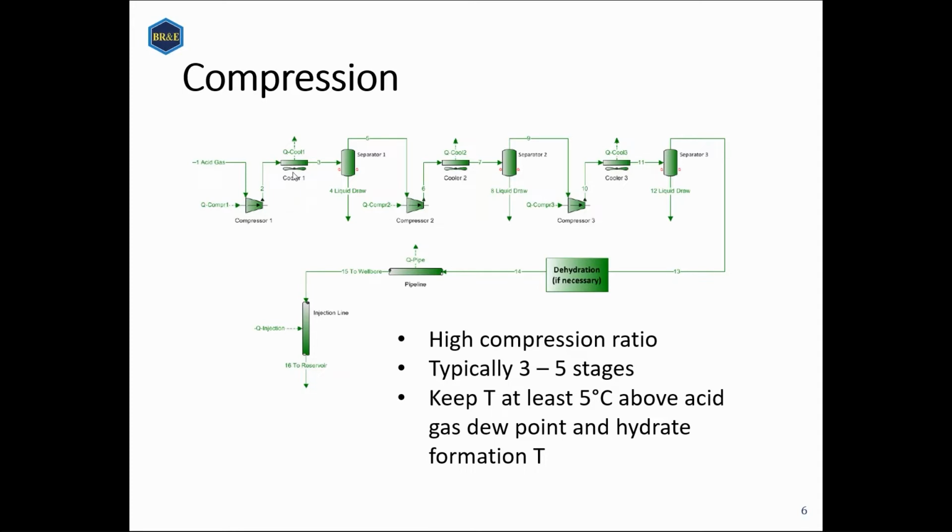So coming off of each compressor, you do have that cooler to keep those temperatures in line. When it cools down, you do have water dropout. There's trace amounts of acid in that water, but the water is going to come out of the system. We don't want to be sending liquids to our next stage of compression. And also it just frees up some space in the system. That's why we have that.